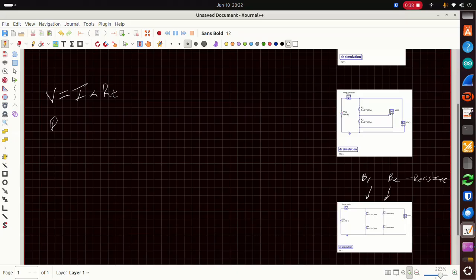All right, so going to look at RT. RT equals 1 over, we're going to call it branch 1 total plus branch 2 total, and it's 1 over each of those. So RT equals 1 over branch 1 total plus 1 over branch 2 total.